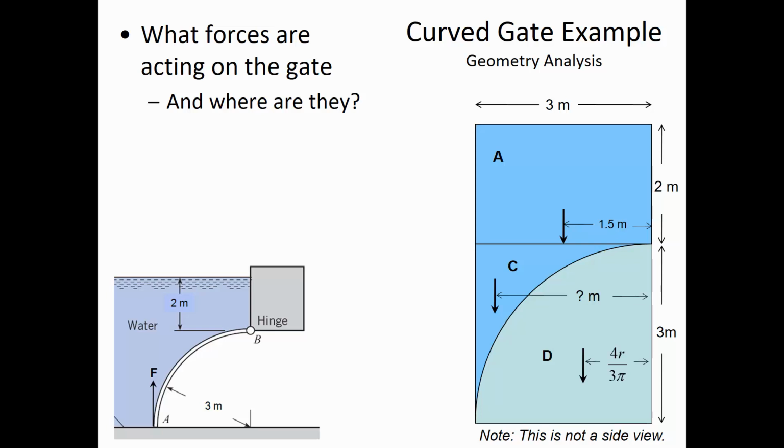So the volume there is 28.274 cubic meters. And so then C is the difference between the two. So it's 36 cubic meters minus 28.274 cubic meters. So 7.726 cubic meters is the volume, just of this little thin strip of water that's immediately above the gate.